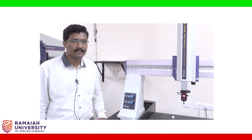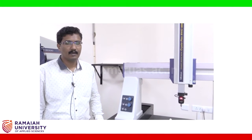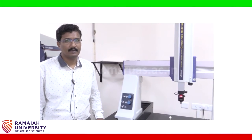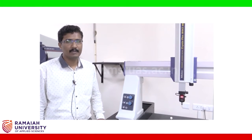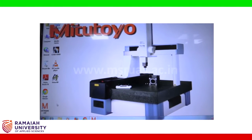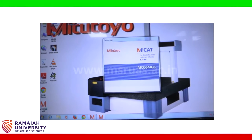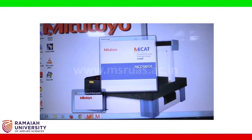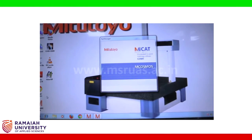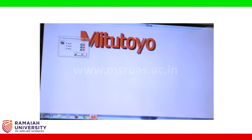Now the next step in preparation of the CMM is to bring the axes to the home position. We have mCosmos software which will help us in doing the measurements and homing. Now next, you open the mCosmos version 4 software. Now let us open the mCosmos software and complete the homing operation.